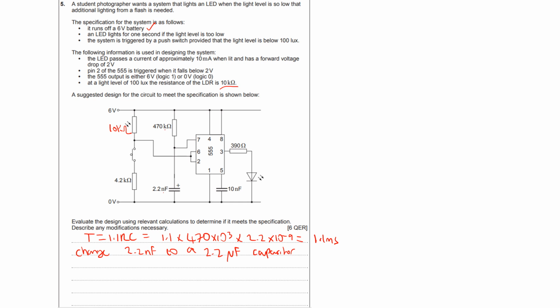So I would say this system will not be triggered, as pin 2 doesn't drop to 1/3 of supply.